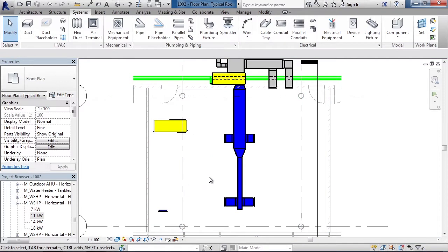So in this lesson, we looked at placing air terminals and mechanical equipment. We talked about placing your main system components first, your mechanical equipment, your VAV terminals, AC units, your HP units. Once those were placed, we then went on to place our different types of air terminals, our air diffusers, our air supply grills. We also looked at various colors and why those colors are the colors we see on our screen: yellow, blue, magenta. And finally, we looked at an overall layout of placing these elements inside of the view.